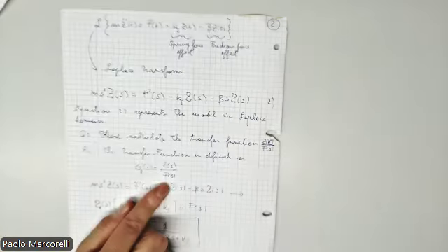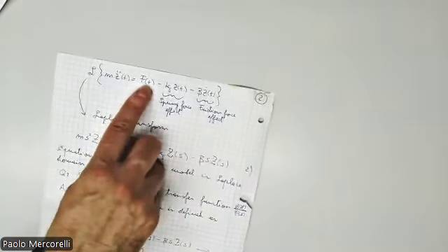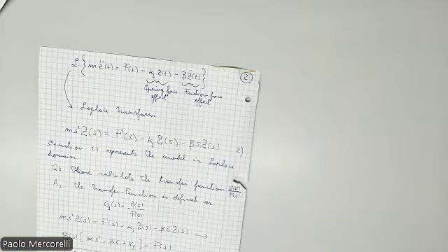For instance, if the input here is the force, typically in this representation, we have the force, we reflect the energy which I put in as an input, and the output could be the position, could be the velocity, could be the reaction force, could be the acceleration, everything which you like. Could be also just the spring force, could be also just the damping force, everything which you can localize as an output in this equation could be considered as the numerator of the transfer function.